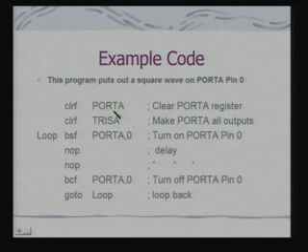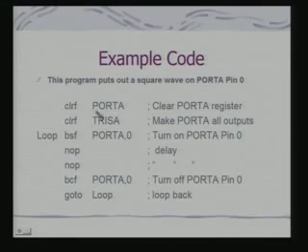The next thing is, these ports can be I/O ports. Okay, that means each pin can be configured as an input pin or as an output pin. Now, if you are doing that, then I need to pre-program that port and each pin of that port. So, in this case, we use a register called TRIS, and for each port, since we are talking about port A, we have a TRIS A register, and we are clearing the TRIS A register, making all pins of port A output pins.